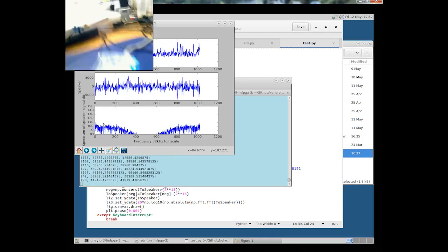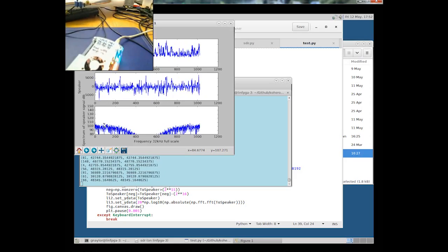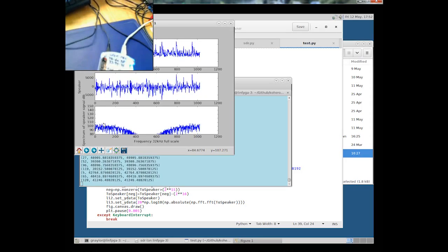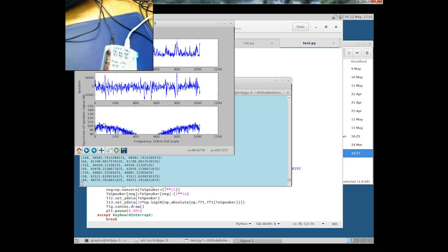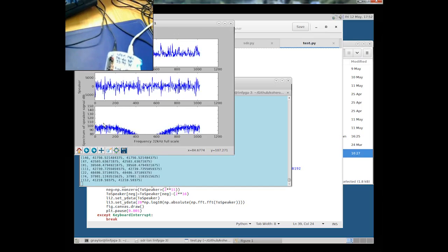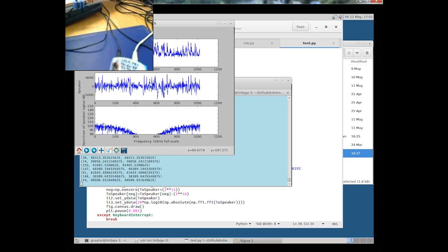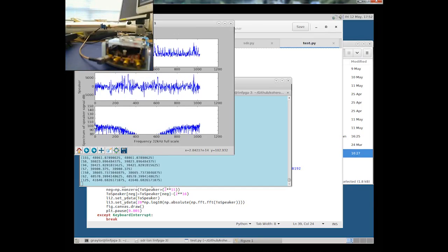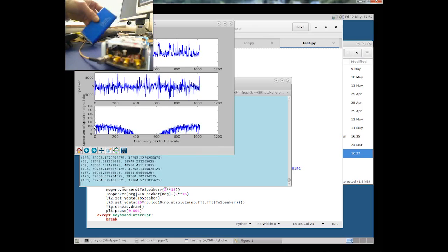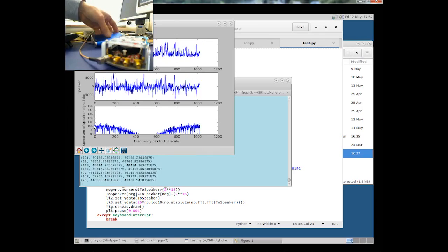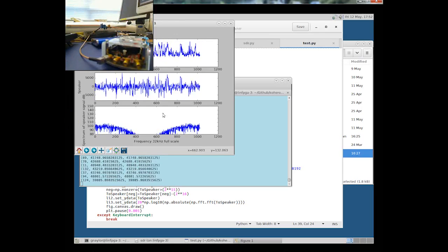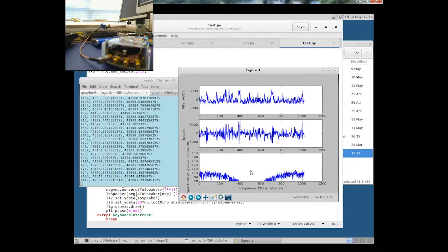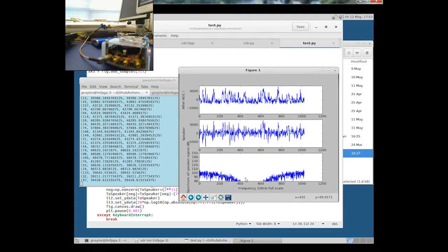Now if we look at the LEDs now, they're pretty well fully lit up. One of the reasons for that is that we're getting a lot of noise from our USB input signal, which we're just taking from a simple mains supply, which is actually putting in a lot of noise. So we'll have to replace that with a battery device. So to do tests, we'll use something like this, which will give a lot more stable 5 volts. But anyway, already we're seeing some signal here, and we can now go and do some tests.